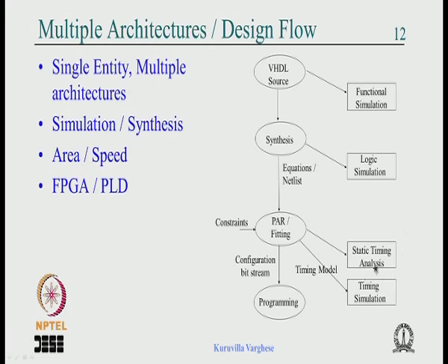But when you do static timing analysis there is no way for the tool to know which path is active and which is not, because you are not simulating it, you are not giving a clock, and the controller is not active. It is just the addition of the various block delays, and the real behavior of the circuit is not known. That is known only if you really give the inputs and simulate it. So static timing analysis is a quick estimate, and you have to tell the tool some paths are not used, which is called a false path. Maybe from source to destination, everything may not happen in the next clock cycle.